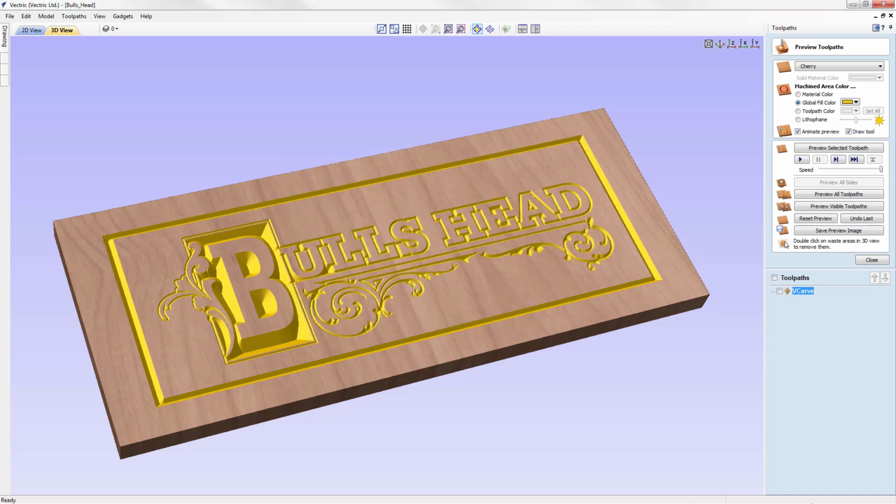So even though we are explaining the steps to create this sign in a lot of detail, you can see how quickly it is to open the vector file, alter the job setup, select all of the vectors and center them in our job, then take those vectors, switch over to the toolpaths tab, double check over the material setup, create the toolpath, calculate it and preview it here. We could have, in theory, got to this stage within a minute of starting.